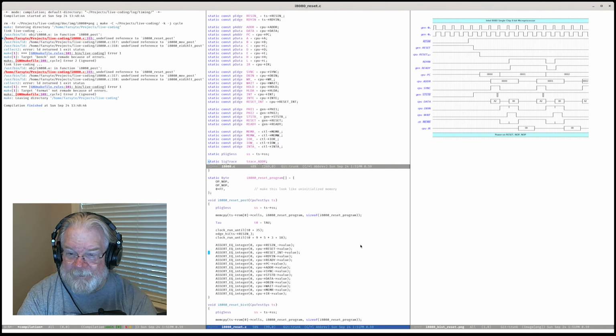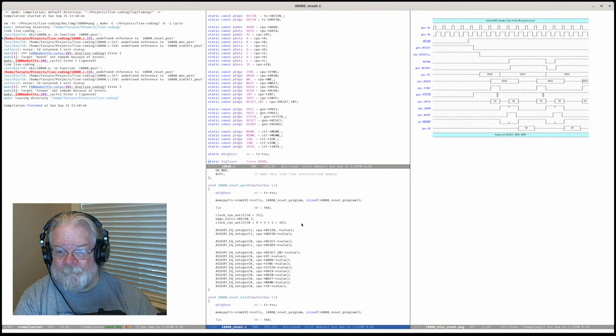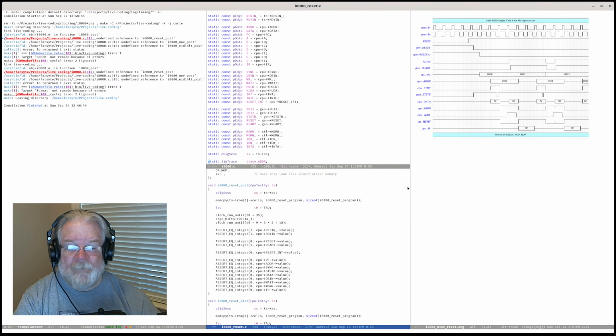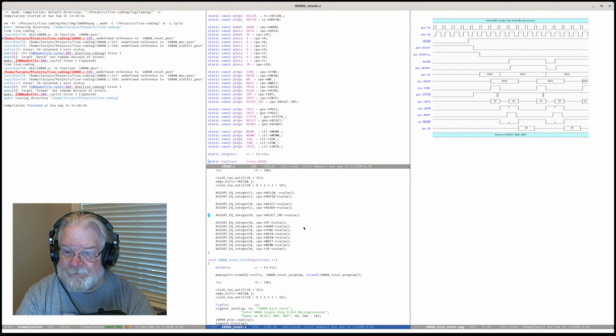So we are going to assert that at the end of our reset test, reset and ready in got manipulated. Reset and ready got manipulated by the test. Okay. Res in went high. Reset went low. Reset internal went low. So these are things the CPU does, and we're going to move stuff up that the CPU didn't do.